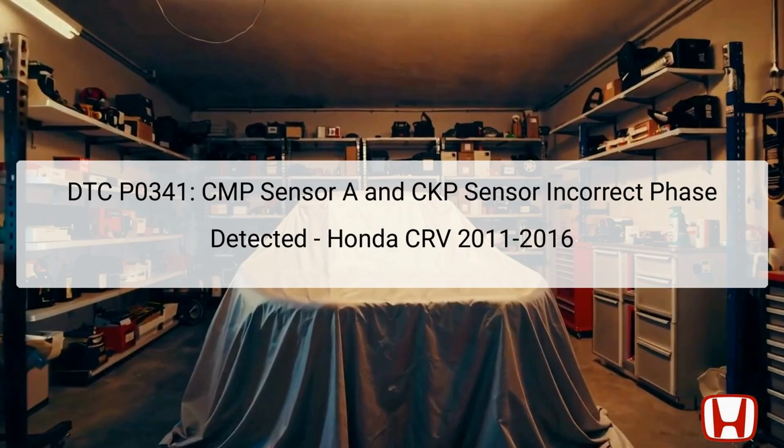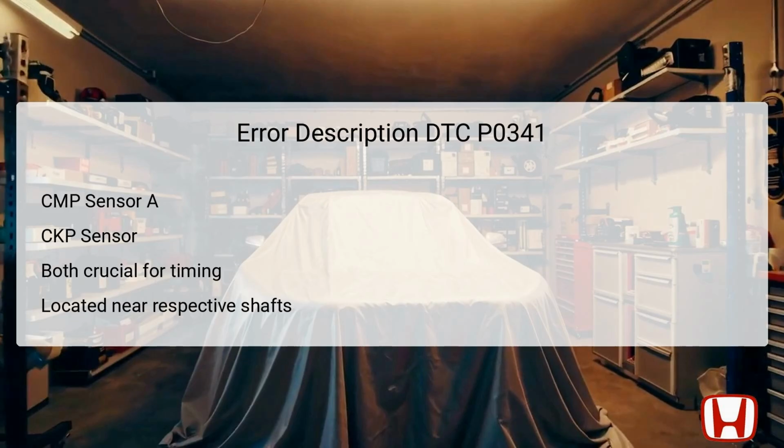The diagnostic trouble code, DTC, is triggered when these sensors fail to synchronize their readings, which can lead to various engine performance problems and even engine stalling in severe cases. Before beginning diagnostics, it is crucial to record all freeze data and onboard snapshots for further analysis. The Honda Diagnostic System, HDS, is utilized to read the DTC and execute the necessary troubleshooting steps outlined in the manual. DTC P0341 is defined as the CMP sensor A and CKP sensor incorrectly detecting phase alignment.